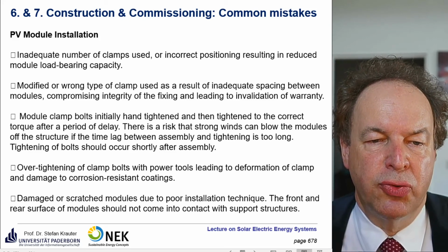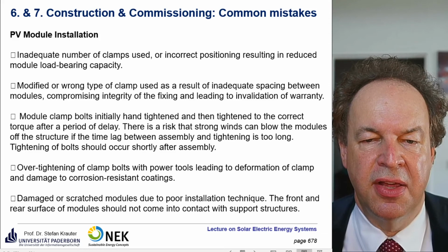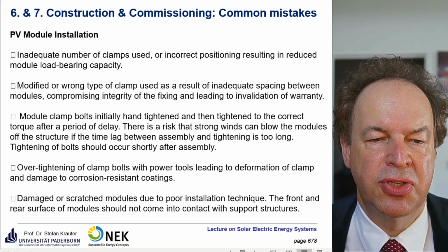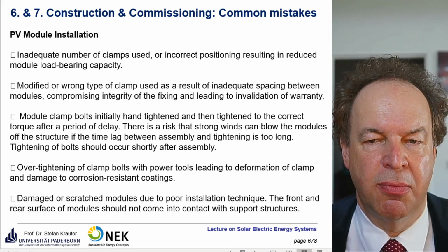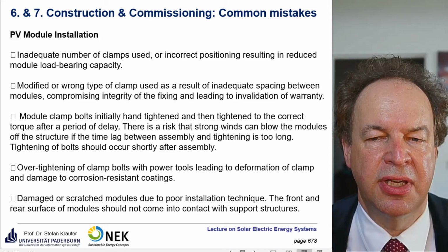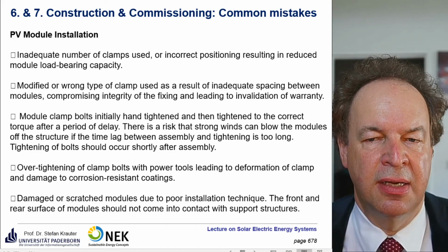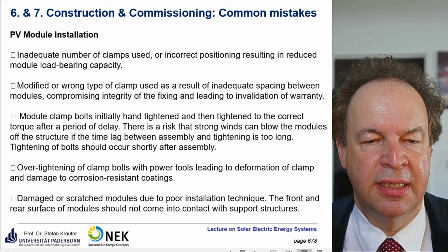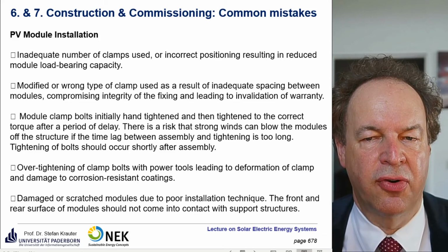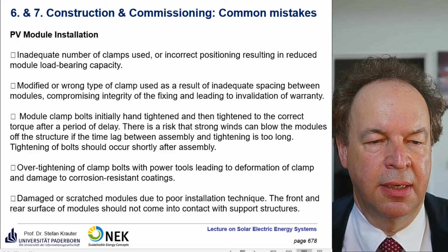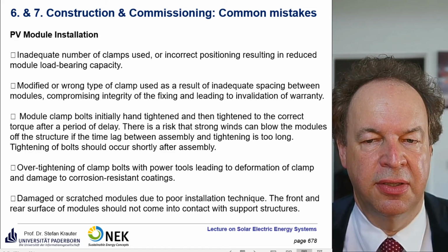Damaged or scratched modules due to poor installation technique. The front and rear surfaces of modules should not come into contact with a support structure. This is also due to electrical safety. It's specified that the module can only be fixed via the module frame, and it really should stay away from any metallic material, especially the back part.